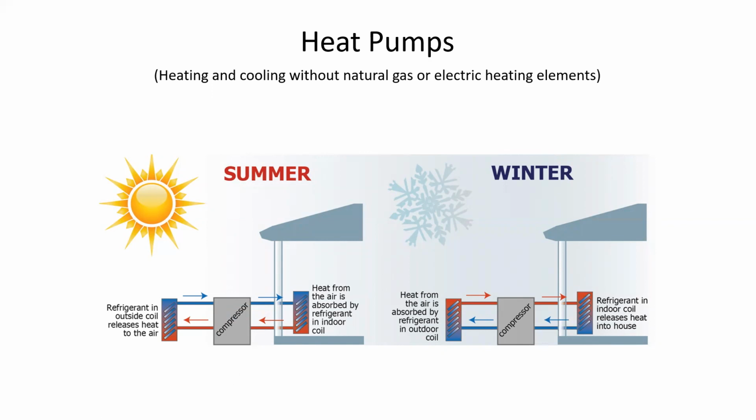Now, heat pumps have a definitive threshold of temperature that they can operate within, which means that a heat pump is really only useful in fairly temperate climates. Heat pumps are not able to remove heat out of air that is too cold. A -30 exterior winter atmosphere will have so little heat energy in the air that a heat pump would not be able to collect it and dump it inside the house.